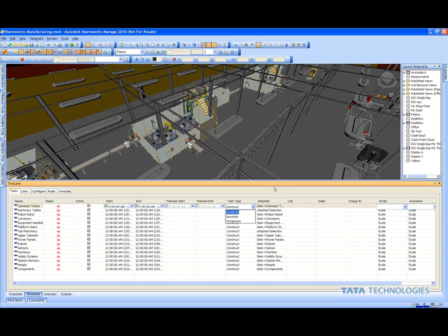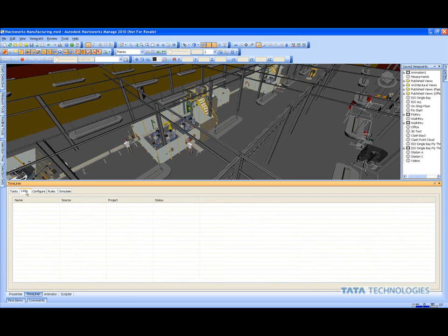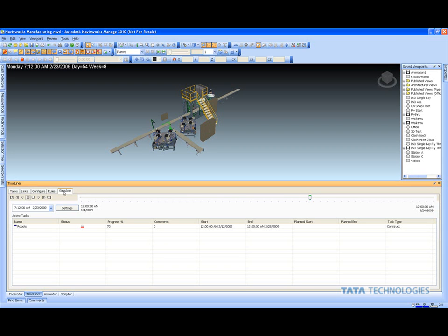Also with this, as I mentioned from the PowerPoint, we can link to some of the leading softwares out there for project timeline. There's 3 that are already showing up, and there's actually more. As long as we have the software loaded, it would also show up in this list. But out of the box, we have Microsoft, Primavera, the CSV file, so different ways we can link that project information into Navisworks. On the simulation side now, we can actually go through and understand our designs a little bit better. The simulation itself is going to read from our timelines as needed.